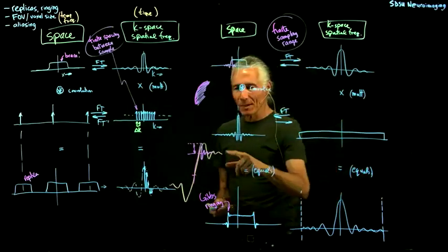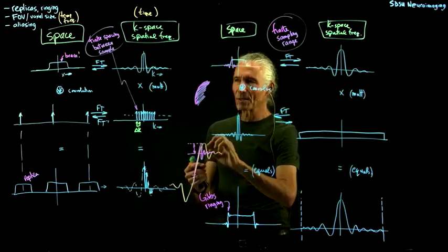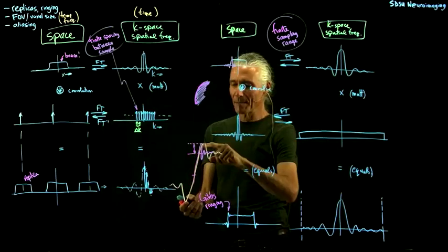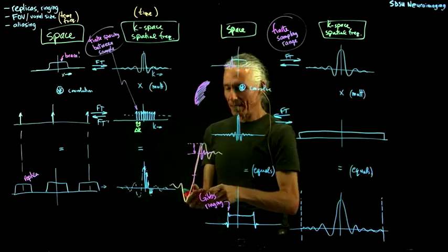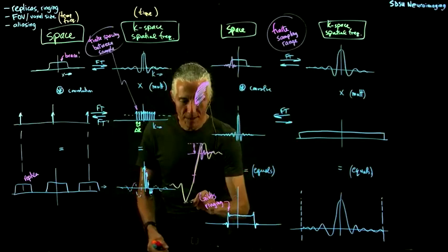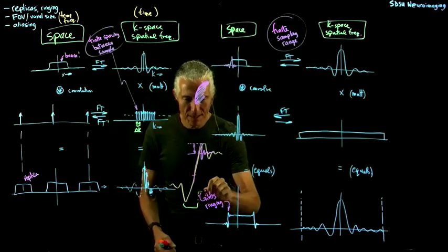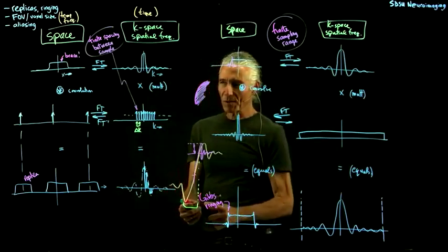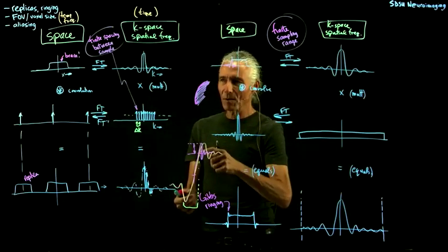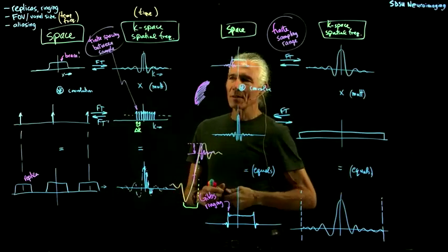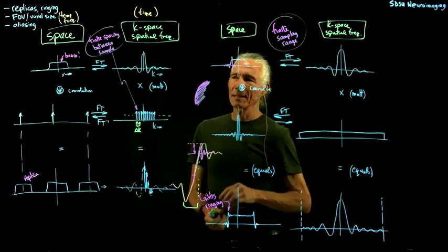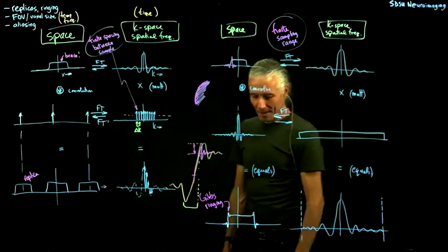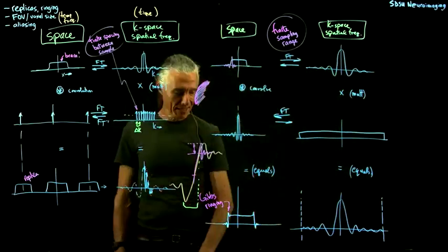So there are various ways of fixing this. One way is to very gently smooth. If I run a smoothing filter across this little region, it will squash down those high frequency little spots at the cost of slightly blurring your image. So that's the Gibbs ringing.